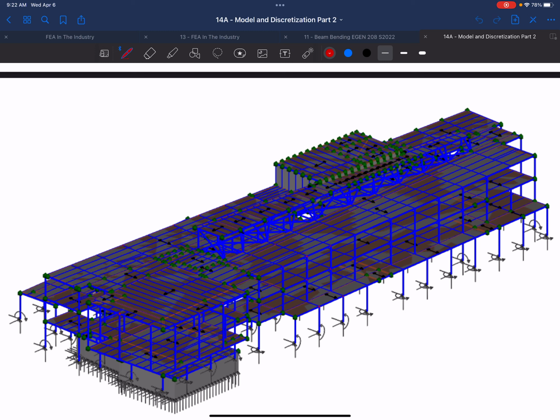So you want near 1, is that what you're going for? Yes, but it depends. You always want it close to 1 for the most efficient design, but there's strength, and there's also serviceability, right? There are deflections you have to take into account. So not only are you going to AISC to look at the strength, but then you're going back to the IBC to look at deflection requirements, and make sure that, you know, the beam should have L over 240, right?